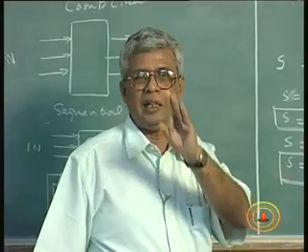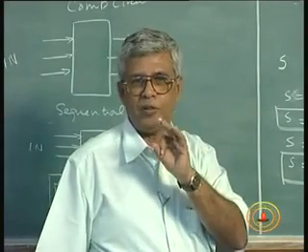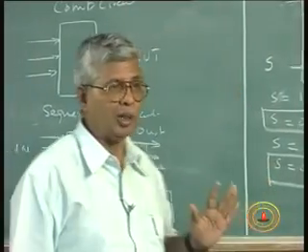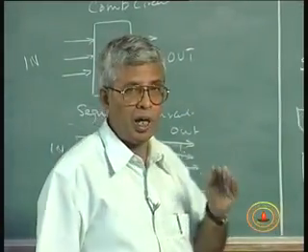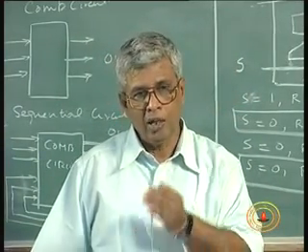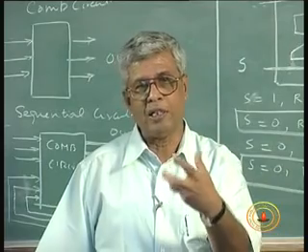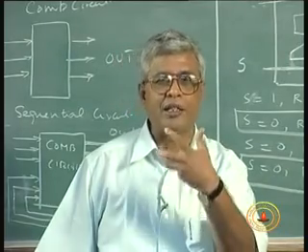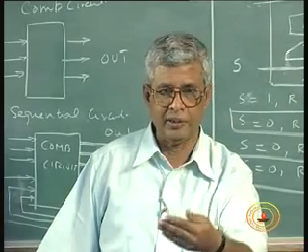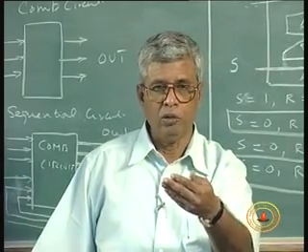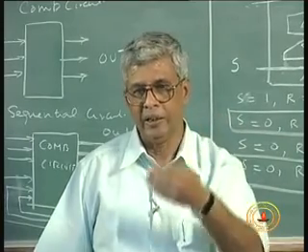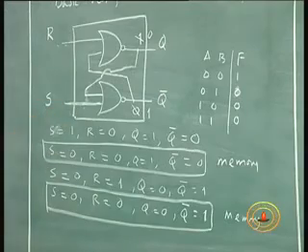So this is the basic component of memory, which is the fundamental building block of a sequential circuit, in addition to all the combinational building blocks. Because combinational blocks cannot be dispensed with just because we are going sequential. All circuits will still have a lot of combinational blocks, but the sequential part is what determines the operation, the event driven sequence of operations. What the output is now depends on what the output was earlier. All that will be done by the sequential circuit because there is memory in it. So that is the basic stuff.